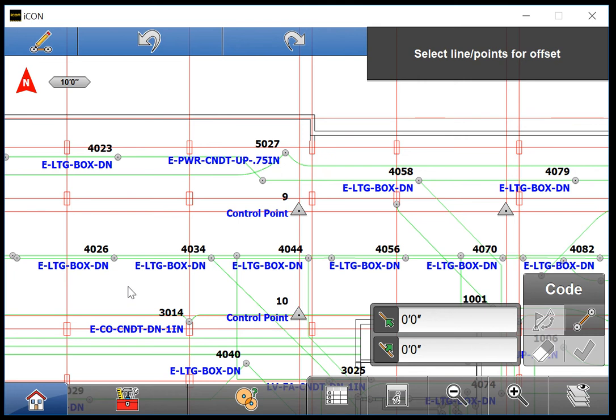Let's say we've arrived on the deck, they've flown the tables up, but the only marks that we have fall in this area inside my mouse. We only have one control line intersection, and we need 2 to set up the total station. This is where we could lay our tape down along this line, or along this line, make a measurement, and mark directly on the line. Let's say we measured 20 feet in this direction from this intersection.